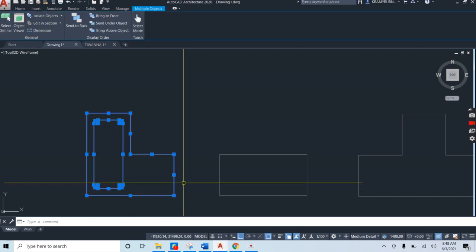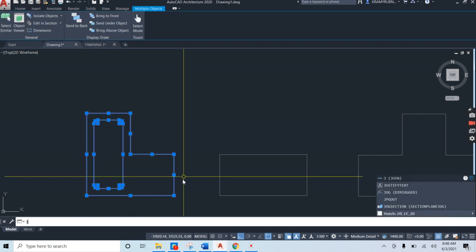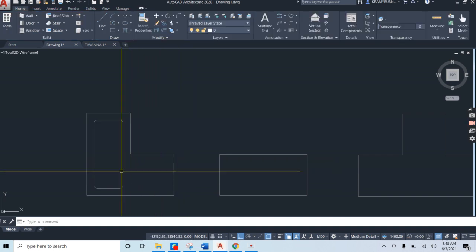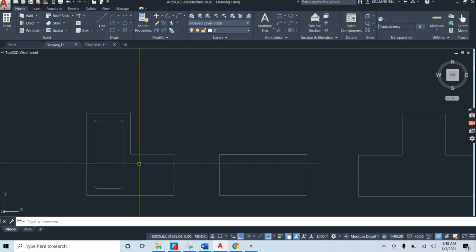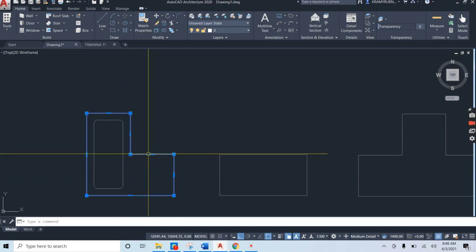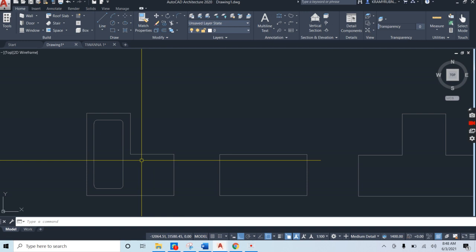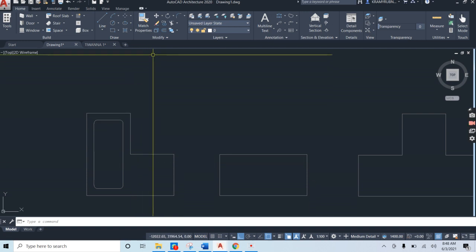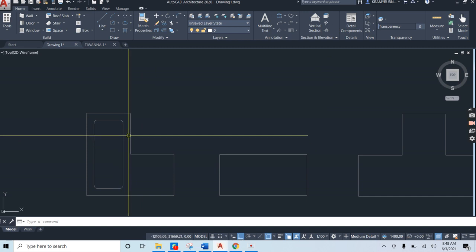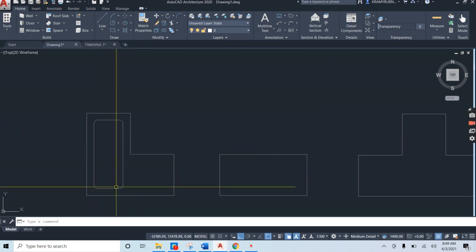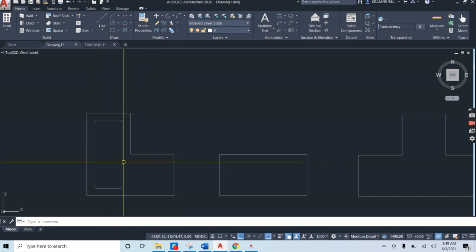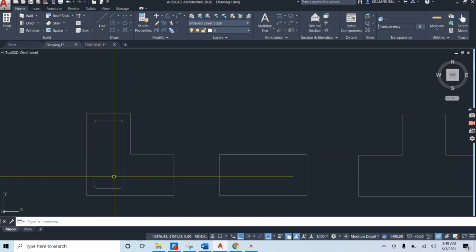So let's select everything, give J, enter, just to test that my link has been connected, and also that my stiffener is connected. Well, now let me go ahead and isolate or hide this stiffener, giving me clearance or clarity to prepare my other stirrup.